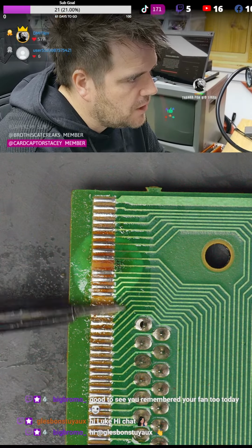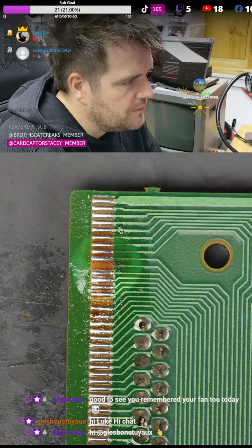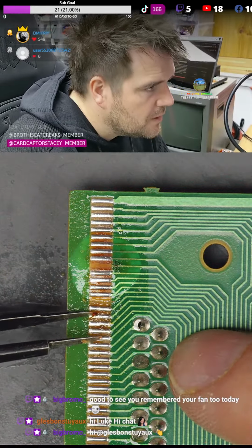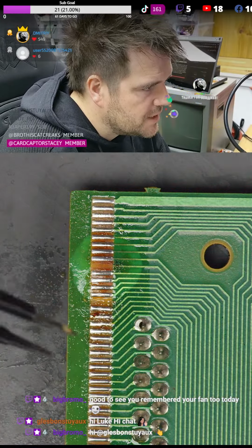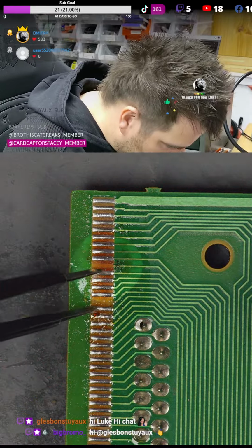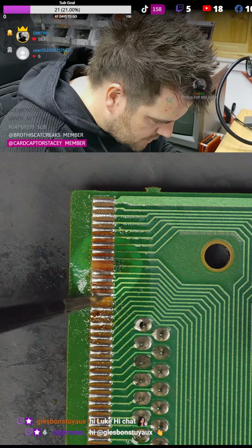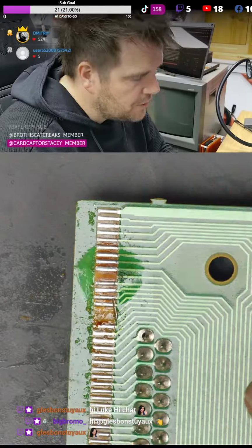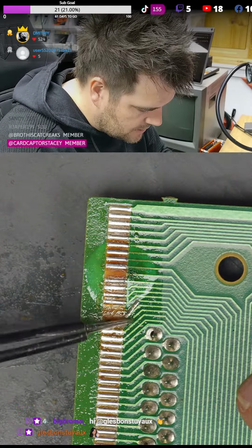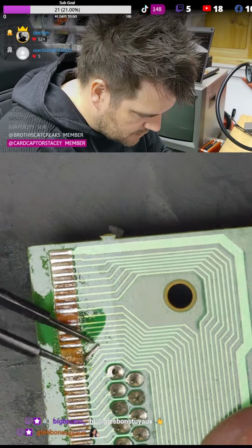I'm going to wiggle them off, and we're going to redo them when we put the connector down. We're going to make them onto the traces. I don't want potential weak connections looking like they're good, but they're actually weak. So let's finish the job and terminate these.